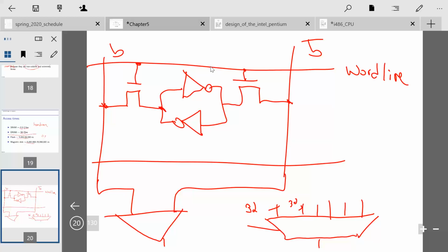And so longer lines, whether it be the longer word lines or the longer bit lines, add delay, because remember, we try to make the memory array as square as possible because it reduces that delay. The optimal delay usually comes from a fairly square memory array, because it shortens the word lines and the bit lines. To access this array, the most significant bits of your address go through the row decoder, which has a propagation delay, and then the row decoder lights up one of these word lines, and that selects a row of memory.